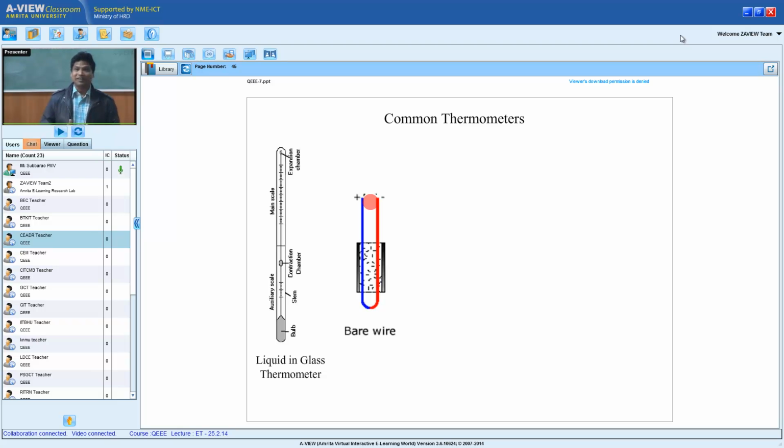Now see the beauty. If this voltage can be transmitted to kilometers, and that can be digitized, stored in a computer, and the computer code will understand these digits and try to control the system. Now the question is, how many millivolts is 0 degrees? How many millivolts is the steam point? How do I know? Now I need to have a thermal equilibrium between these two. So in order to know how many millivolts equals the ice point, and how many millivolts is the steam point, again I need a kind of equilibrium.